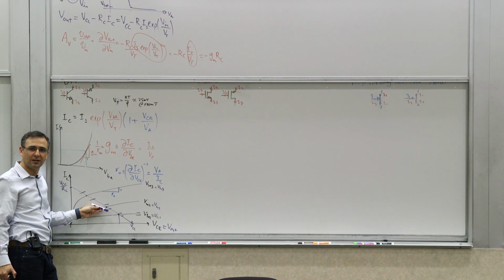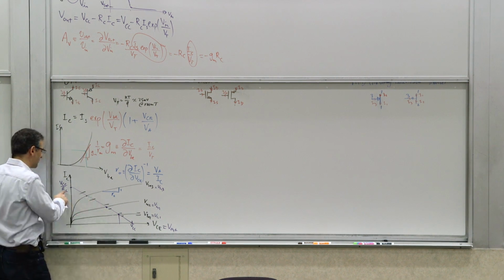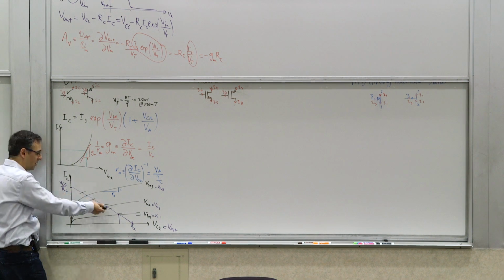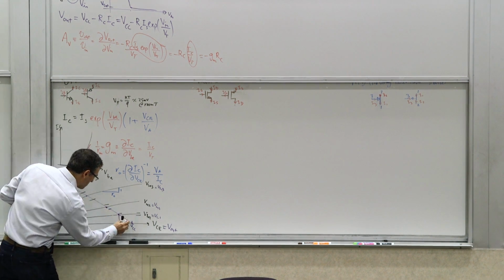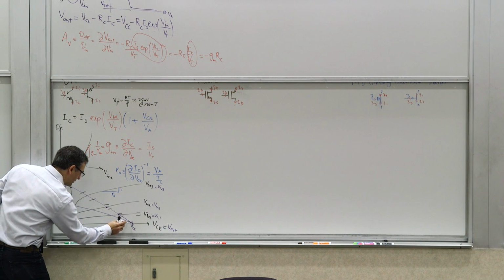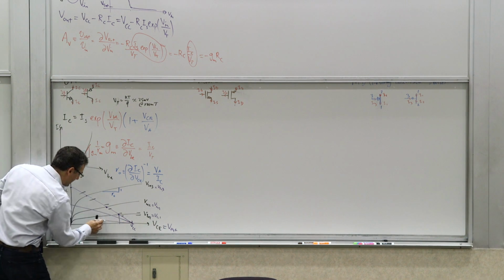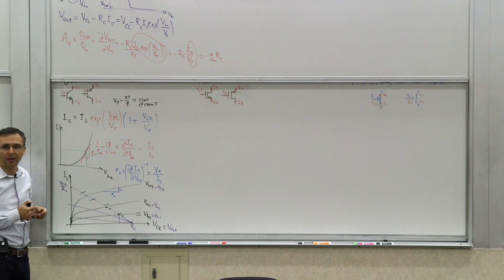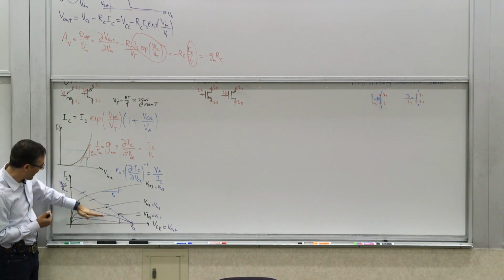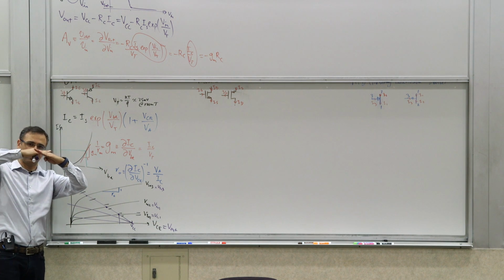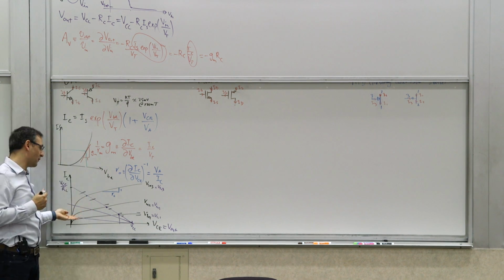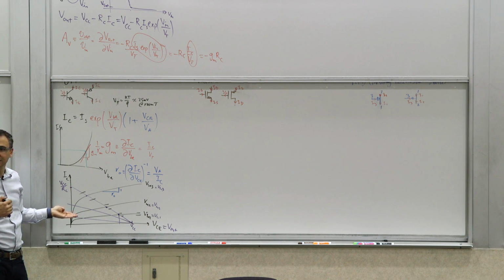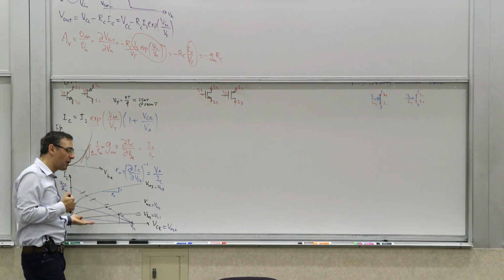Less steep, right? How do you make it less steep? You make RC larger, right? As you make RC larger, this load line becomes shallower, like that. And if I make RC larger and larger, it becomes shallower and shallower. So apparently I get more gain, because now I have two things that are almost aligned. There's a problem with this, obviously, which we'll solve later. But what's the problem with this?